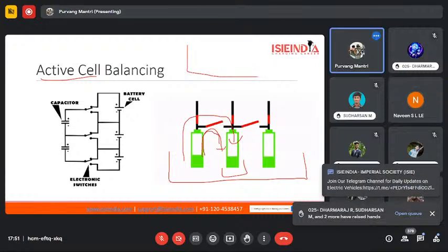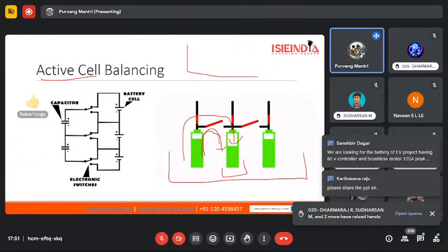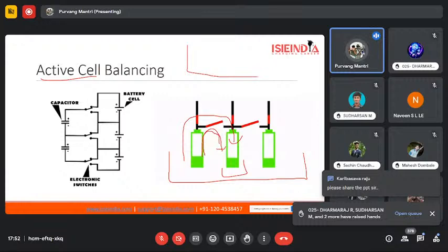Even in my case, we are using lithium-ion batteries in our cell phones. I don't charge the battery pack to 100%, because the BMS of our electronic devices like cell phones is not programmed like the BMSs of our cars. So in that case, you should charge only to 80% and discharge it to 30%. Doing this, you can have a longer lifespan of lithium-ion batteries. This is actively done by the BMSs.